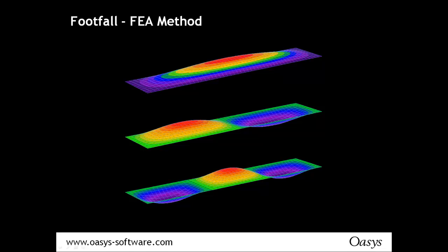Loading as well, you need to include the loads, you need to include all the credible dead loads plus some of the live loads. Unlike static analysis, it is not conservative to take maximum loads. If you take all dead and all live, you'll get a lower response because the mass resists the accelerations.